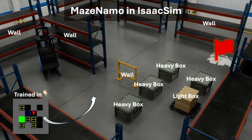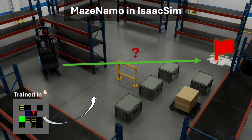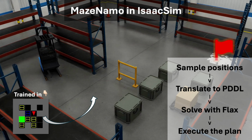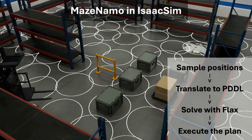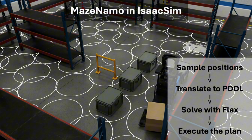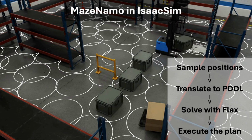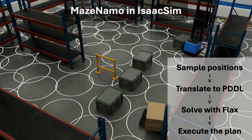At runtime, we tag every rigid body with a semantic class and extract the center of its bounding box. Each center is mapped to a symbolic position. However, real-world environments often contain large free areas. If left empty, they can block the symbolic search for valid paths. We therefore sample additional stepping stone positions by packing equal radius circles until saturation. After sampling, the new positions are merged with the original objects and positions to create a new PDDL task, which is then supplied to our Flax pipeline.